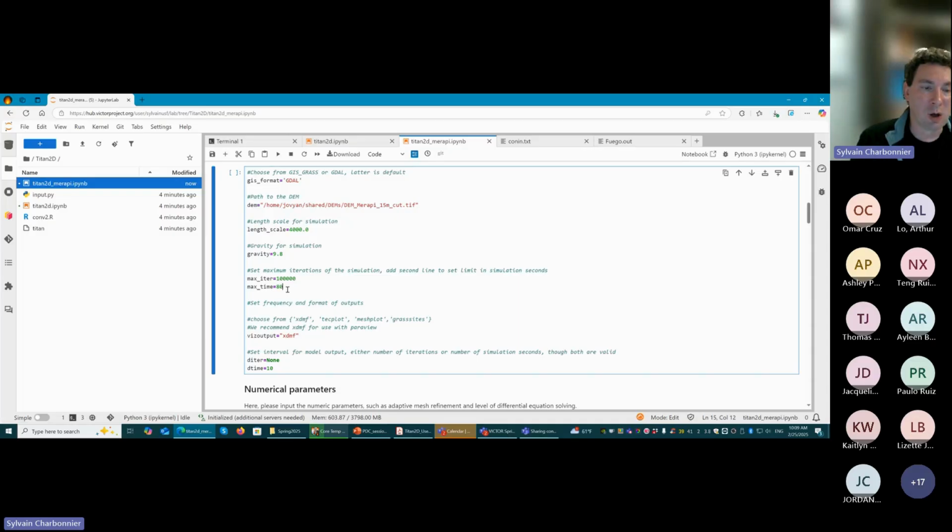So basically, a couple of minutes is good for small flows, and then if you want to simulate flows that are much larger in volume, so this is only half of a million cubic meters. If you want to use larger volumes, I probably suggest that you increase that maximum time to at least 10 minutes, for example, so 600 seconds for a flow that is much bigger. But in the end, you will still have to run several simulations until you find the correct value to use.